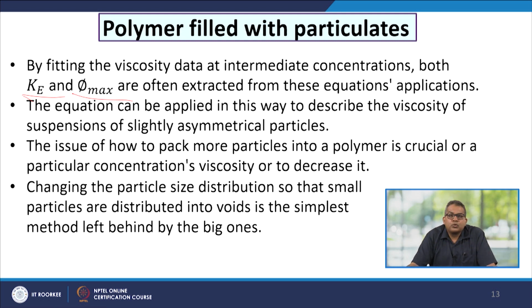The issue of how to pack more particles into the polymer is crucial, either to achieve a particular concentration at lower viscosity, or to decrease it. Changing the particle size distribution so that small particles are distributed into the voids left behind by the big ones is the simplest method.